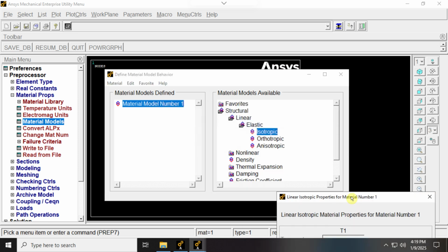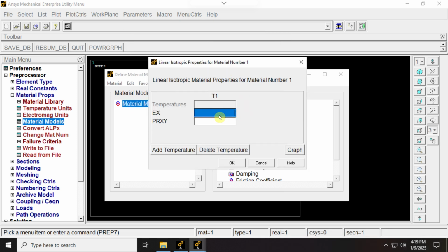Alright, so then here our modulus of elasticity was 10,000 KSI. 10,000 KSI, but I want to have my units in PSI, which is a standard unit. So I add other 3 zeros, and the second one, this guy is Poisson ratio. I'm not gonna need this for this model, so I just put 0.